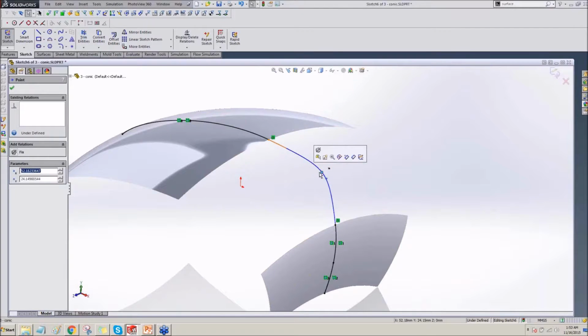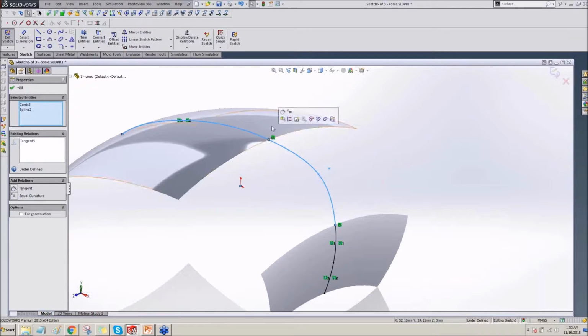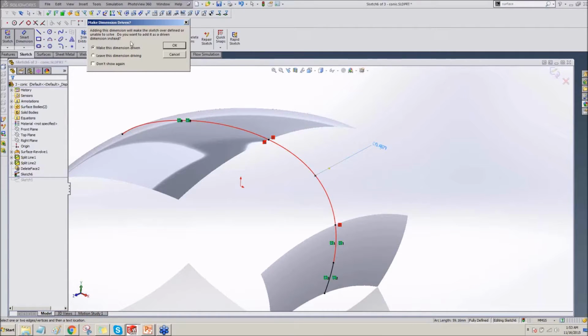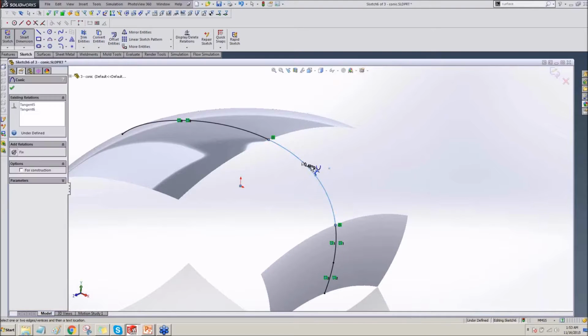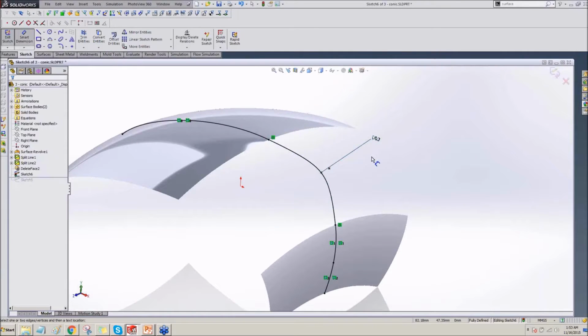Now, as I mentioned, one slight issue is that if I were to set this to, say, equal curvature, it's kind of fully constrained already. The sketch is fully defined. If I have to add a dimension to it, it over constrains it. Of course, if I remove the curvature continuous, instead I can control the conic via rho.